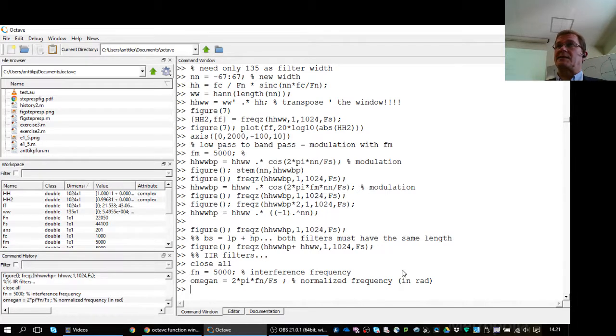And now we set the zeros on that angle. So first the first zero, on the unit circle, e to the J times omega n. There. So that's one zero, but actually we have to have both a plus and minus angle there.